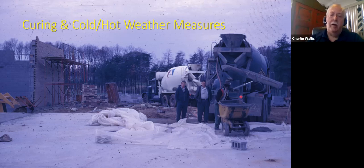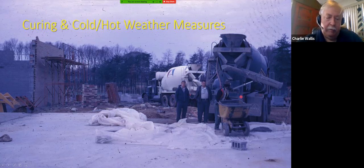And you want to cure concrete. And as shown in this picture, here's some plastic that had been spread over the existing slab that we're looking at. You can use plastic. There's also curing compound that can be sprayed over it, which forms a thin plastic shield, but you don't want the water to evaporate too quickly so that the curing can take place properly.